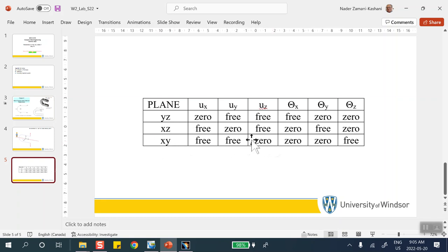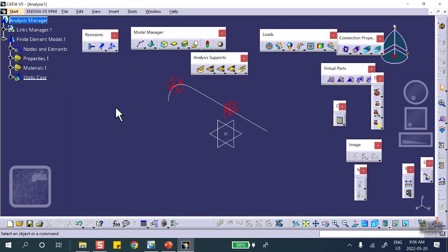These two are free, but you also have to do the rotation. Rotation is exactly the opposite. So if this was free and this was free, this is 0 and this is 0. If this was 0, displacement was 0, rotation is free. Very frequently, people don't do all of these, and we don't give any part marks. You have to do it right. You have to do it for beams. You have to do all of them to get full marks for that particular portion of the problem. Okay? So let's go ahead and do that.